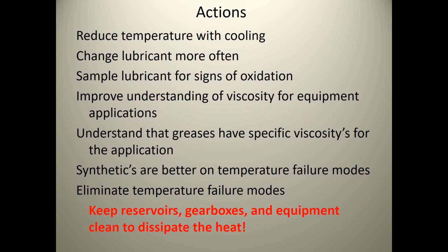On your greases, grease acts as an insulator with this temperature failure mode. Greases have specific viscosities, so if you don't have the right viscosity in your grease, you're going to build up these temperature modes. Synthetics, again, on any application where you have temperature issues, synthetics are better than any mineral-based lubricant. They're better by not changing viscosity, but they're also better for life. They'll last 3 to 5 times longer at the same temperature range as your mineral-based lubes.